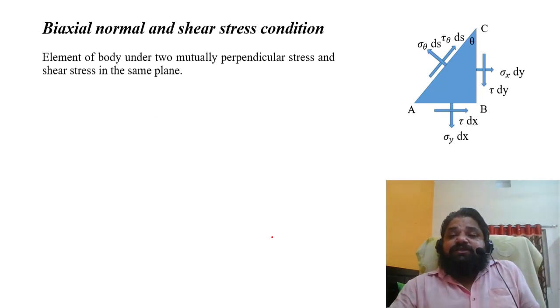If I take a similar way, let's say the cut, and I took this theta, from where to in which angle I am considering, or which direction I am considering, depends upon that. The direction, anti-clockwise and clockwise, will be decided. So this theta I have taken, and on this inclined plane two normal and two stress components will develop, which is a principal stress component, or you can say the stresses on the inclined plane will develop.